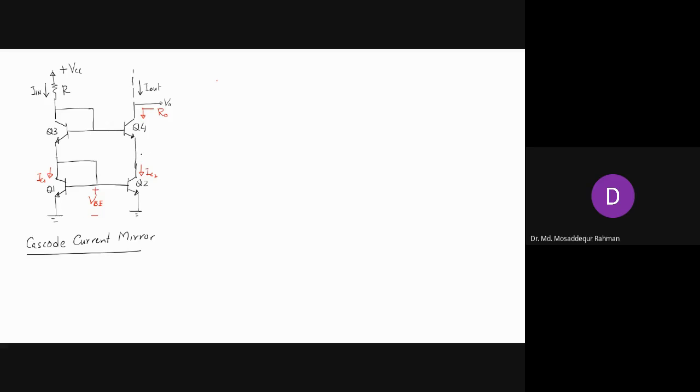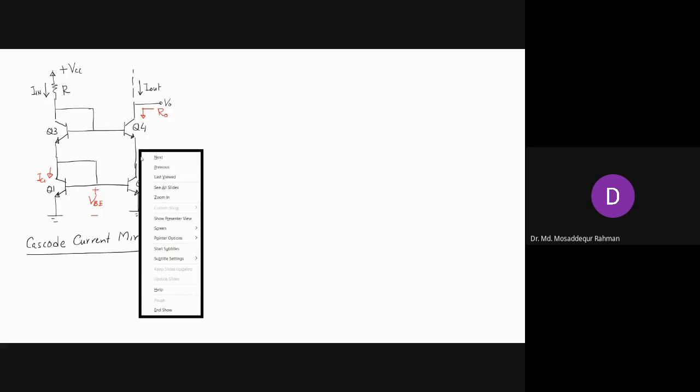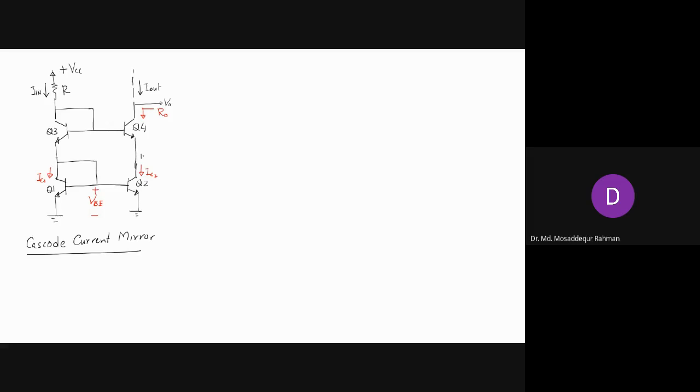Yeah, you're right. So basically, what is connected here at the emitter is the output resistance of this transistor, called R02. And that's the output resistance connected to the emitter, right? So basically the circuit, if you look from the output of the Q4, it simplifies to this circuit.